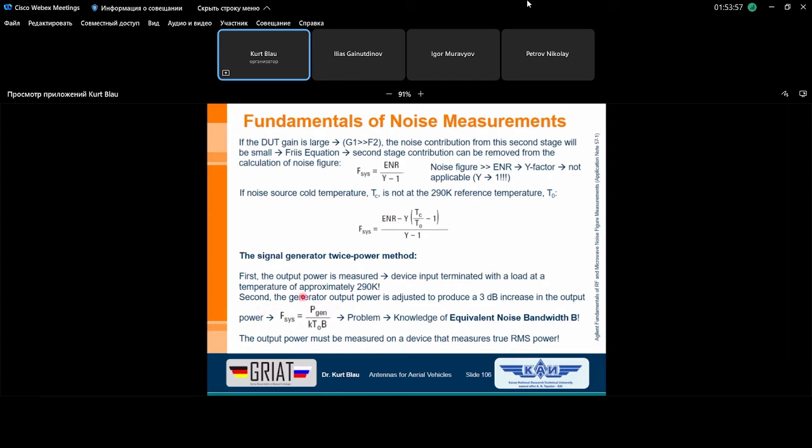We have to notice this value. And this is now related to our thermal input noise power. And we already know that the output noise power is much higher than the input noise power multiplied by the power gain of the amplifier. Maybe such a power amplifier can have a power gain of 1000. It's 30 dB. It's not a problem.